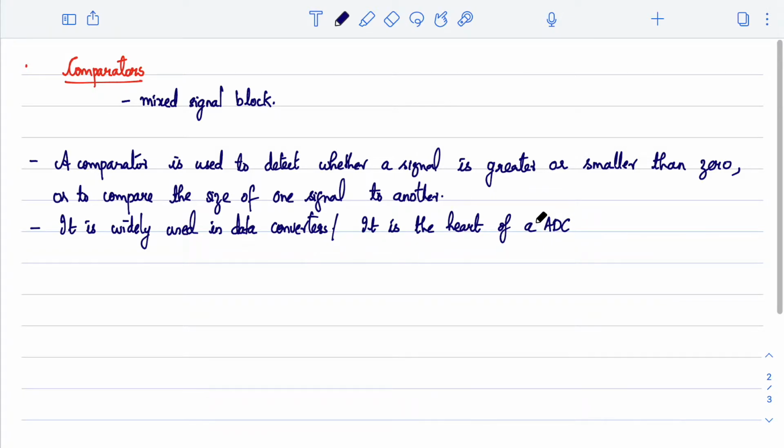Comparators form the central block of a data converter. So if you look at comparator, what it basically does is it compares the signal you have with a reference, and decides whether the output goes to a higher reference value or a lower reference value, right? So in fact, comparators are 1 bit ADCs, where the output says whether the input signal level is higher or smaller by coming to a logic value, whether it is 0 or a 1.